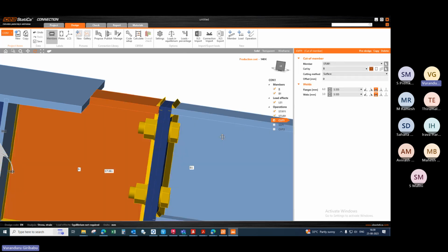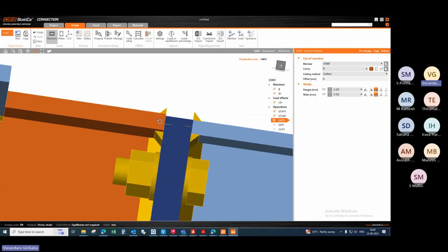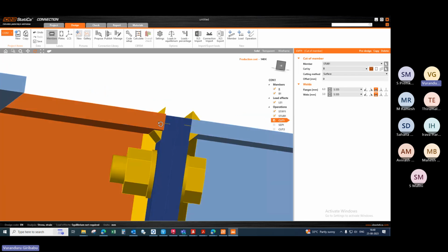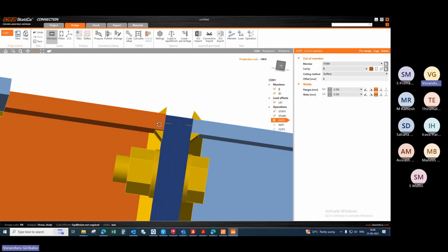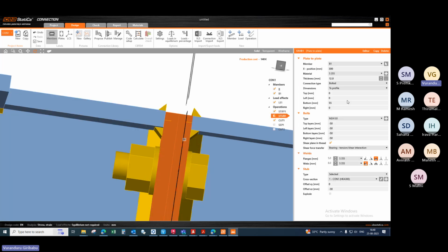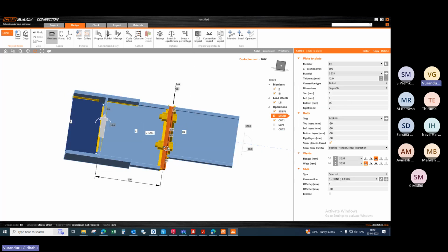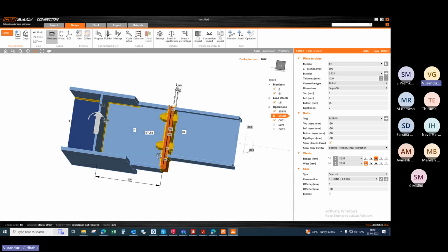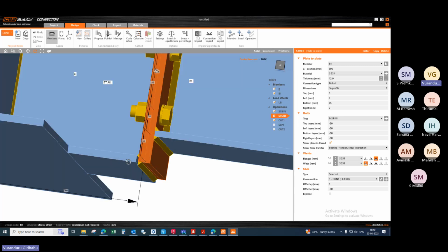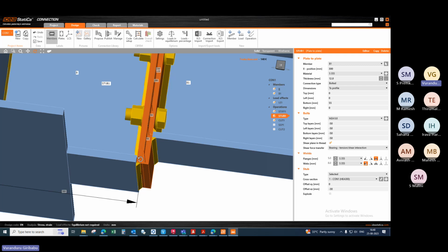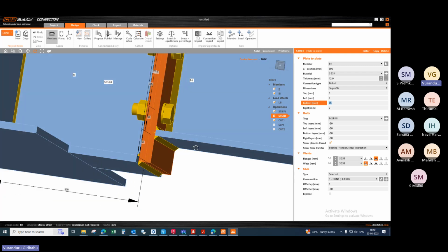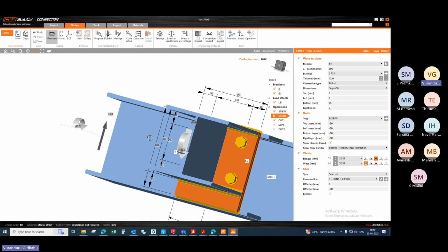Okay, I think right now we can't have the cut in this member, but we can show how we can give the weld in that position. For this stub operation, the remaining thing is the bottom. At the bottom we have 55 mm. It is extended to weld with this flange plate. That is the reason they had given this 55 mm.